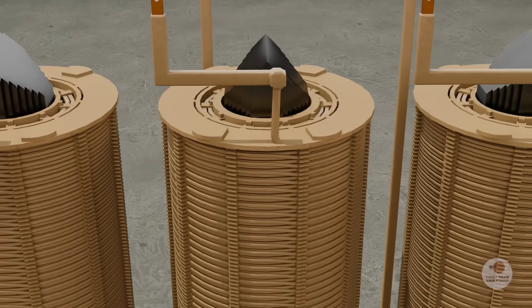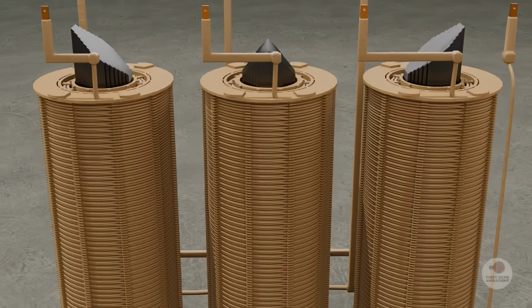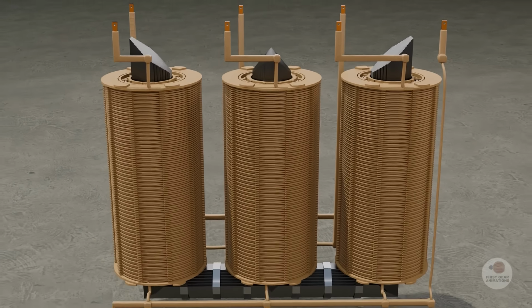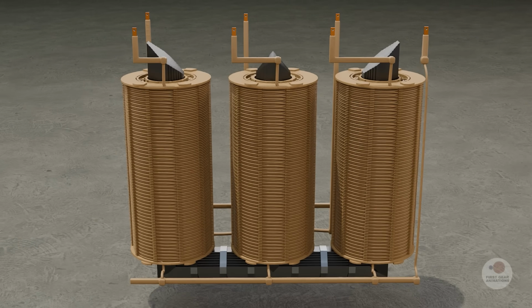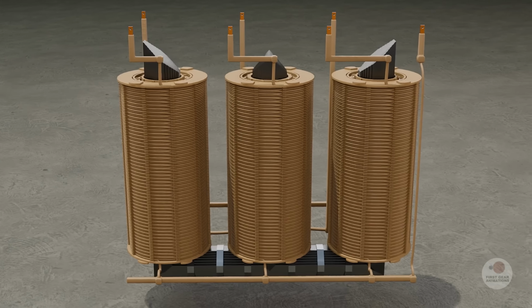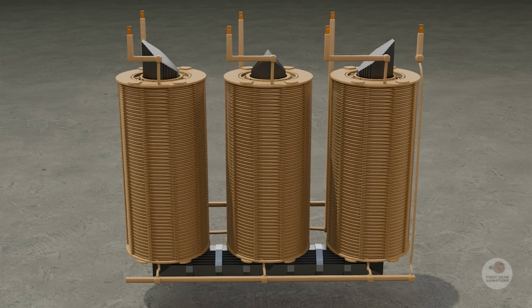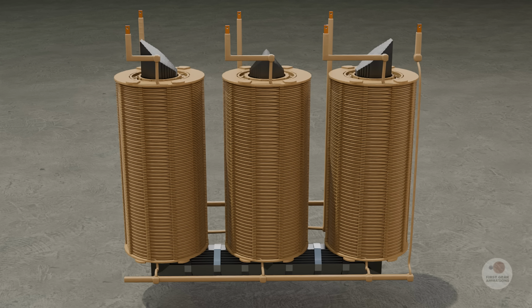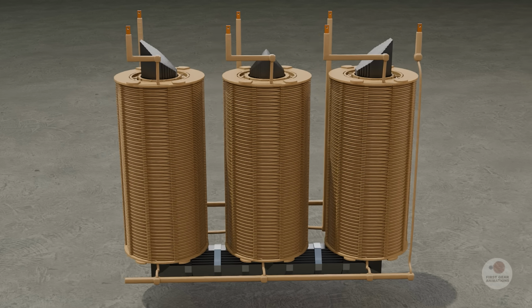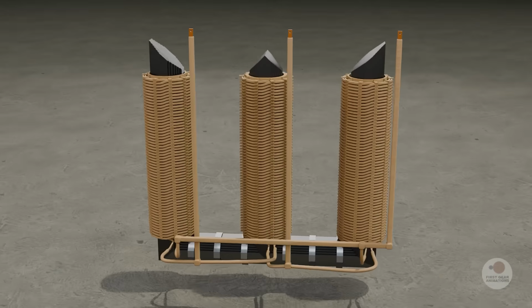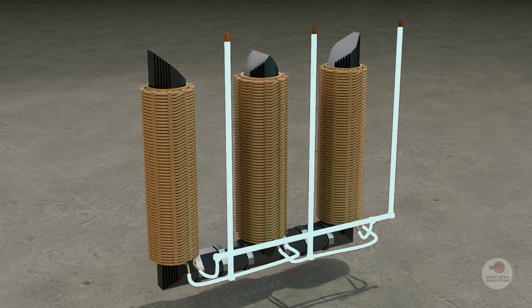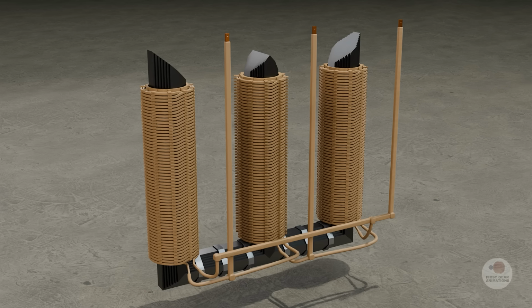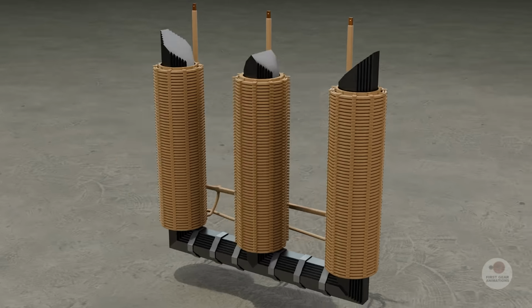Many large power transformers used in transmission networks employ a combination of star and delta connections across their high voltage and low voltage windings. In one common configuration, the high voltage winding is often connected in star, reducing the voltage stress on each winding and providing a neutral point that can be grounded for improved system protection and fault detection. Meanwhile, the low voltage winding is connected in delta, providing a closed path for circulating third harmonic currents. This helps suppress voltage distortion, improves power quality, and enhances the overall stability of the electrical system.